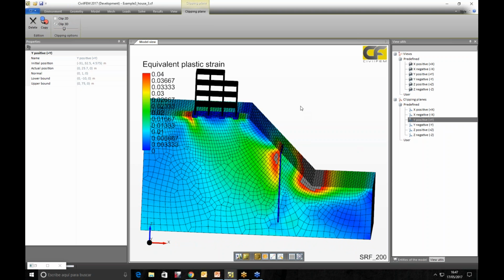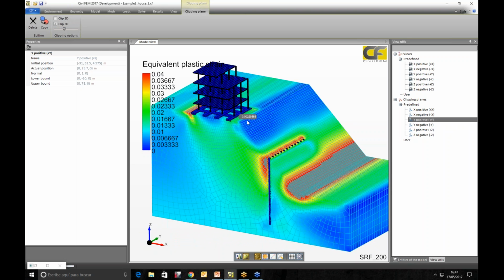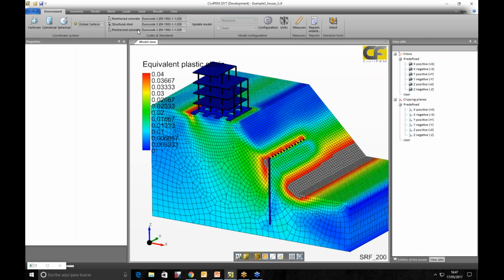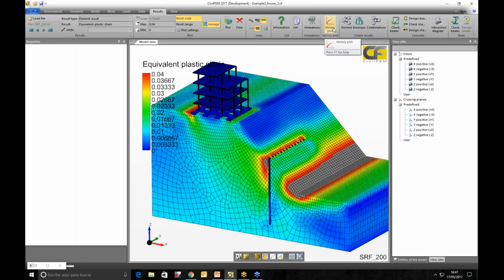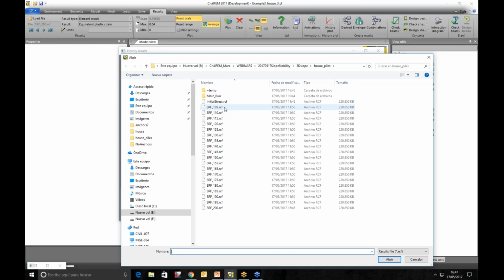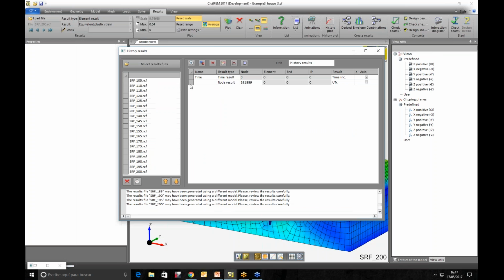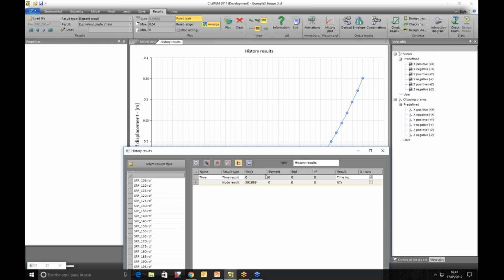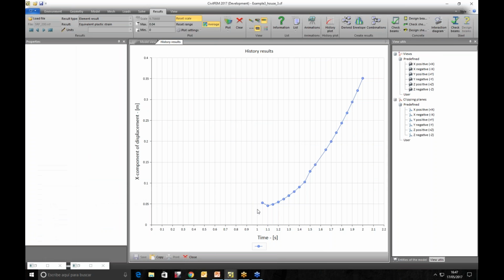part. And well, suppose it's working, we should also plot now displacements versus safety factor to see if we could improve the behavior and reduce displacements, or if we have to modify the piles configuration. In this case, well, we can see we reduce a little bit the displacements. Now for 10 centimeters, the safety factor is around 1.45.